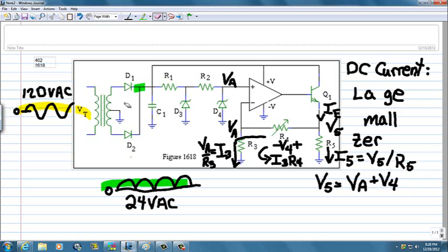These two rectifier diodes will create a full wave signal at this point. That is, they would if this capacitor weren't there. Now the capacitor is there, which will smooth out these positive pulses and make DC that we talked about earlier.